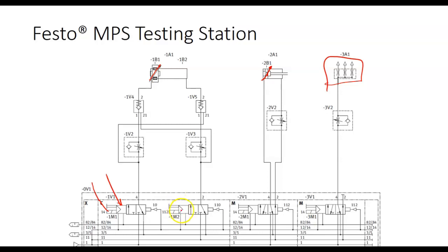Yeah, that would be over here, which would be pilot assist. But these are pilot returns. So instead of using a spring to shift it back, they do the same thing. They lock it in position the same way. But here, instead of the check valves being down here, they got the check valves up there. So what they do here is they energize both of these and shift them over and cause pressure to go here and pressure to go there, and it will lock it into position.